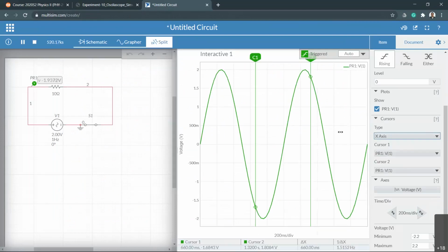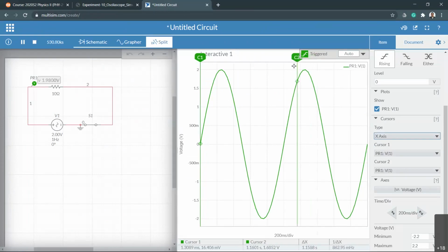And also you can use another way to measure this one. You can put the cursor into the x-axis. Now, if you want to measure, for example, this point, that is the starting point to the end point right here. That is my one complete cycle, right? So that complete cycle will tell you the value of cursor number 1. Okay. So that's another way to measure that one. Now you can see delta x is 1.0017 second, right? So that's what we're expecting, right? So that is the period of oscillation, delta x, the value between the two cursors, C1 and C2.